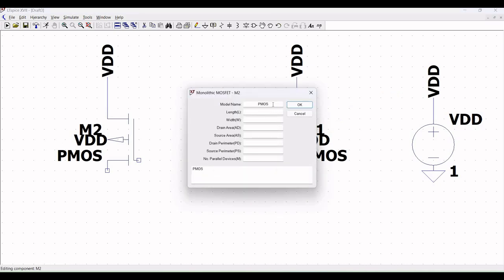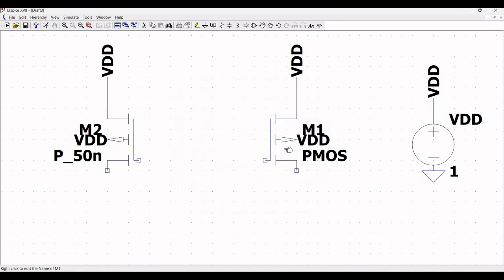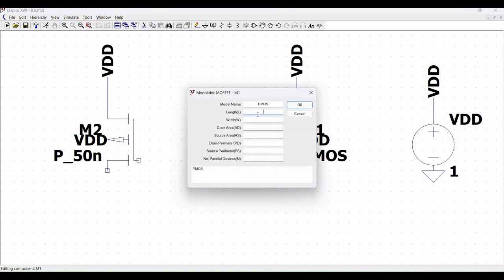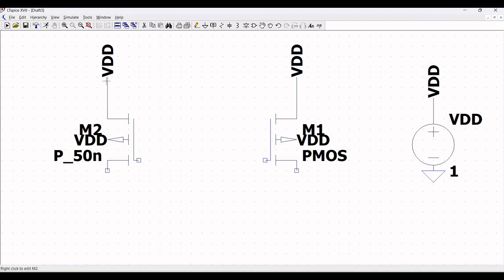Now, in a normal given circuit, a resistor is used to set the bias current that would result in a dependence on the power supply value and the temperature. The reference current is linearly dependent on VDD. The output current is dependent on both the reference current and VDS of transistor M2. So generally we want a reference current that isn't dependent on the power supply or ground variation.